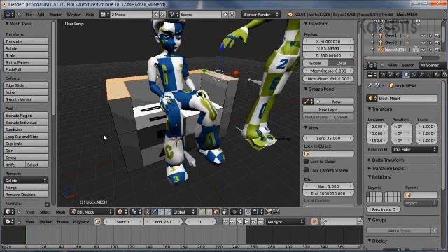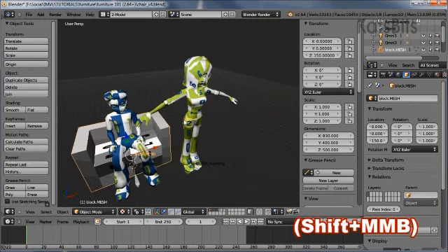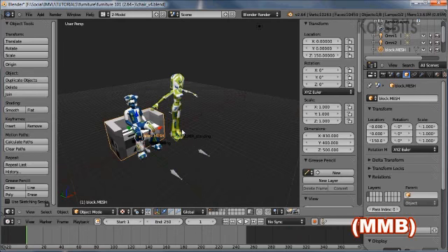Now, to UV edit the mesh, we can do one of two things. The simplest way is to select a number of surfaces and UV map them as groups like that. Or we can do it the complicated way, which is using seams. Now, because we want to see what we're doing here, it might be a good idea to move the lamp object out of the scene. Press the Tab key and exit edit mode. Manipulate your way around the scene so that you can see the lamp object.